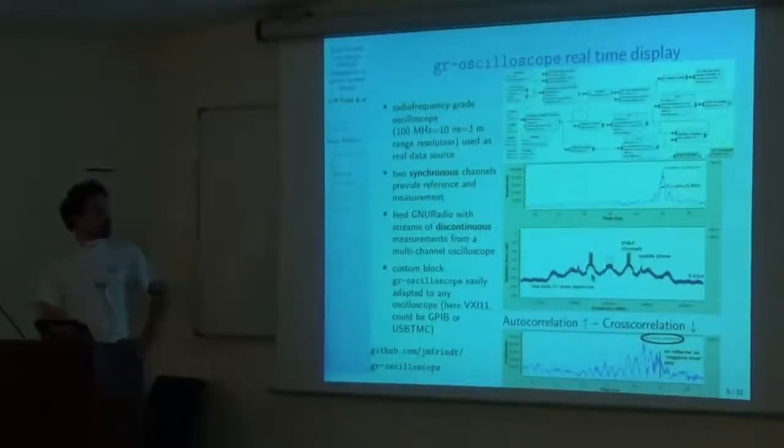Here is an oscilloscope capture of the frequency band in Japan, in Sendai, where you have 5 gigasample per second. So that's actually quite a high-grade, radio frequency grade oscilloscope. And what I did here is I measured from minus 2.5 gigahertz up to 2.5 gigahertz. And here you see your TV stations. So around 500 megahertz are the TV stations. This is the mobile phone. So 870 megahertz is the mobile phone.